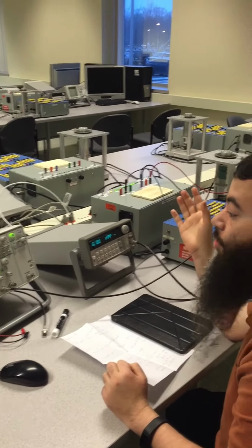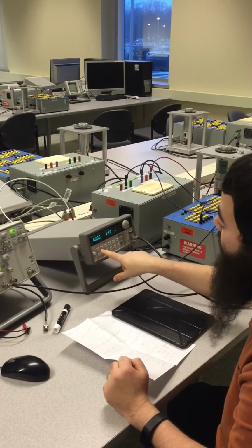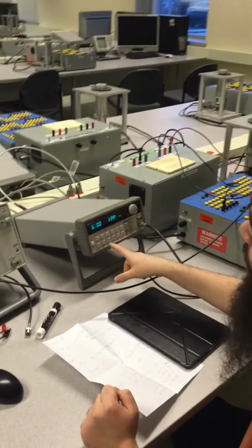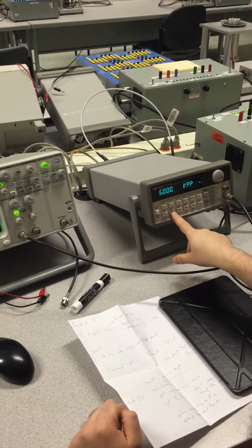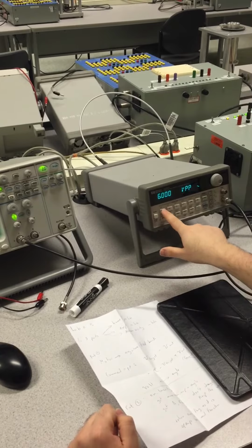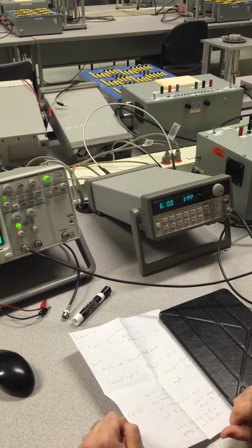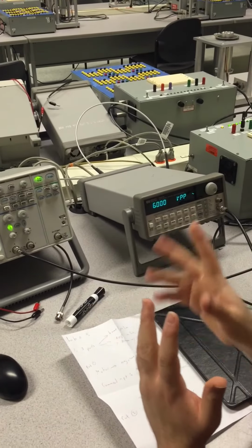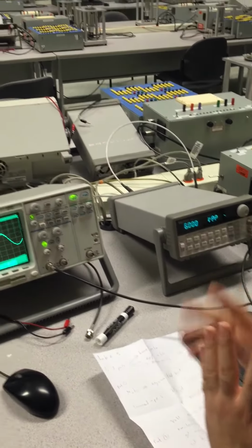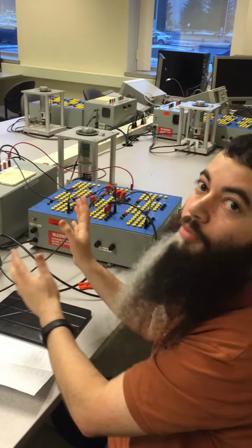The second part of the experiment uses an input sinusoidal wave instead of square wave. So we have the same frequency, 100 millihertz, and the same amplitude, 6 volt peak. But now we will use a sinusoidal wave. Using this experiment, we will find the 2 constants of the motor, A and tau m. A and tau m are specific for each motor. So whatever you get for A and tau m is for this motor